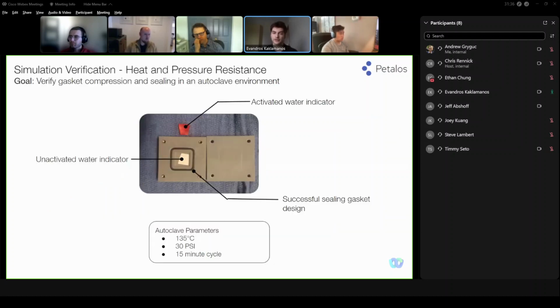During our prototype manufacturing, we decided to assess the performance of our gasket design. We used coupon-level testing for these experiments as the entire controller body isn't necessary to inspect sealing and gasket compression. During these tests, we assessed whether the gasket compression of our current design was feasible. Here, we can see that the gasket compression of our device is sufficient as no leaks occurred.